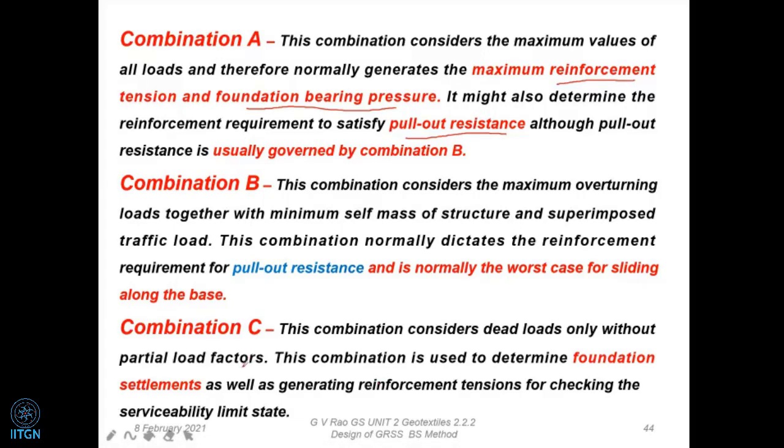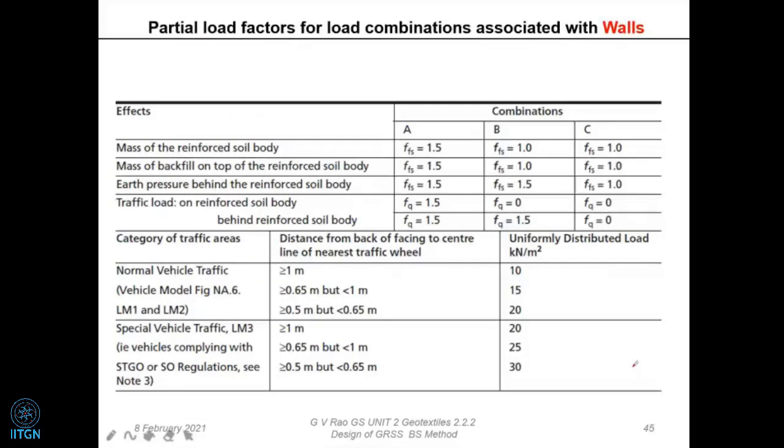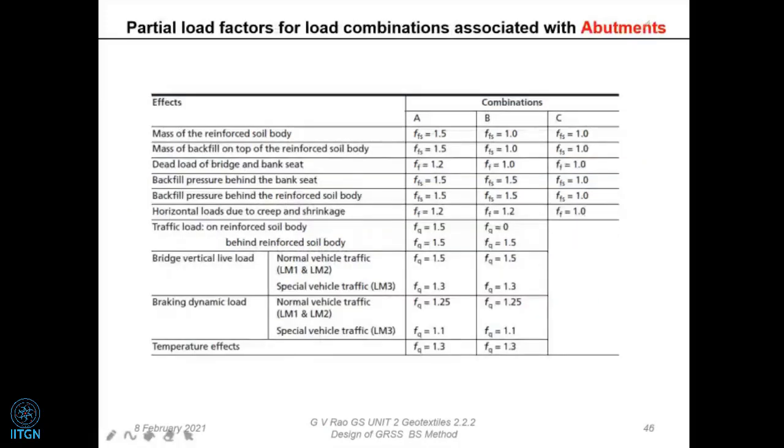Other than that, a more important thing is it's going to be critical for foundation settlement. So that's how the serviceability limit state is also going to come in. The factors we have in the picture are only small elements actually. This particular one gives you the entire range of loads which are going to be there. This is for walls, and for abutments also. Various factors, vertical load and dynamic load, braking load, many things are considered.